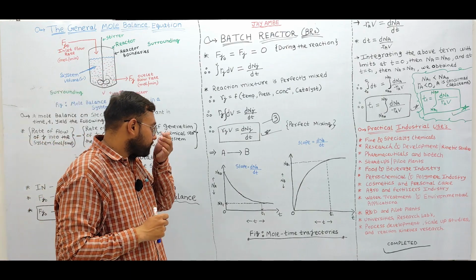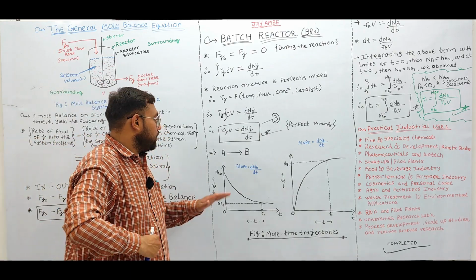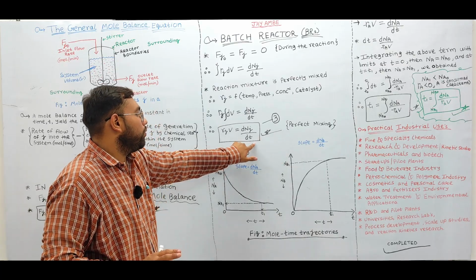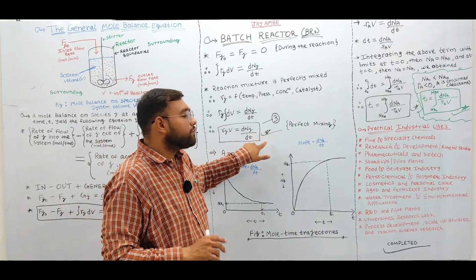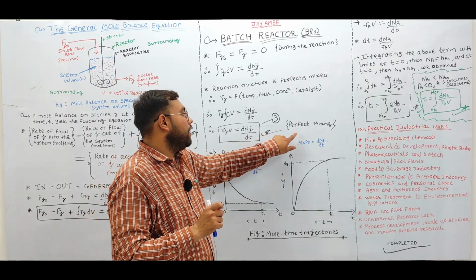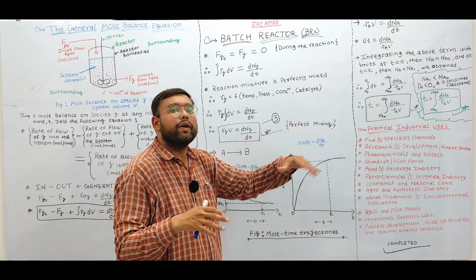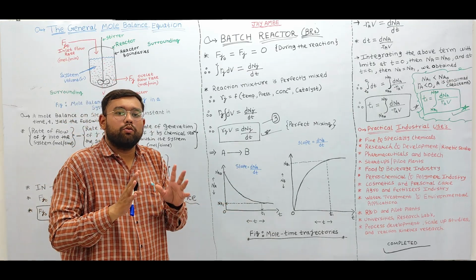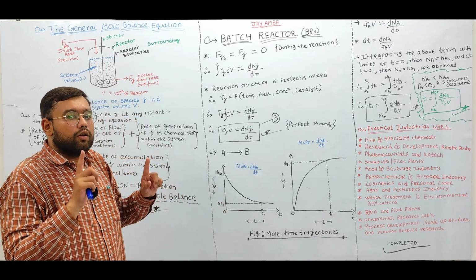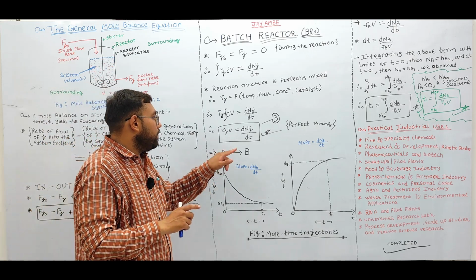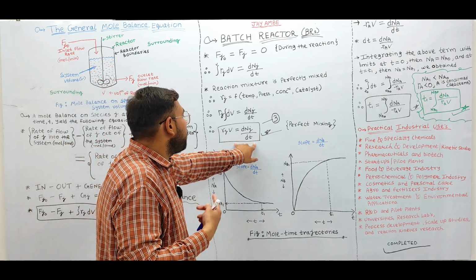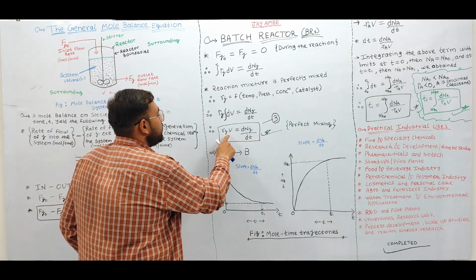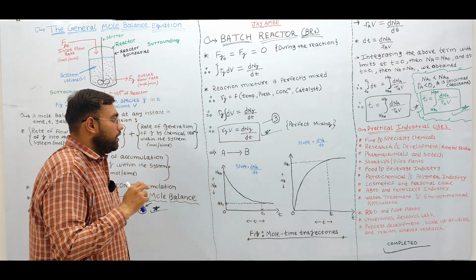Up to here it is clear, right? This form of equation, when we have the condition of perfect mixing, meaning uniform mixing of all the system variables throughout the entire reactor volume, gives us the differential form of the mole balance equation, which is indicated by Rj V is equal to dnj/dt.